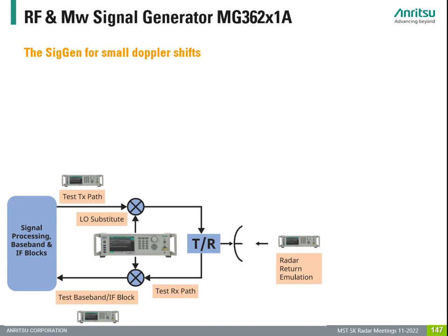That's the catch-22 here. Weather radars are high-resolution velocity radars, while air defense radars have a large range of velocity detection, but the accuracy in velocity is in just the tenths of knots. There are cases where it is necessary to be able to distinguish between small or very small Doppler shifts.